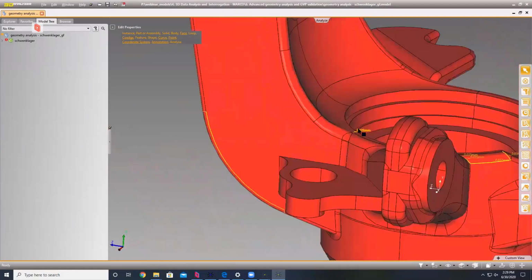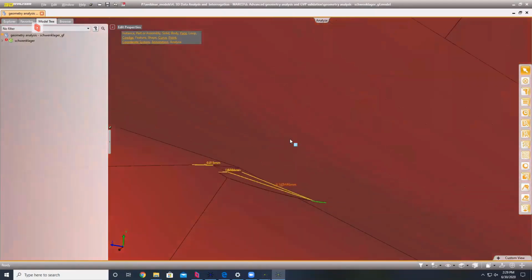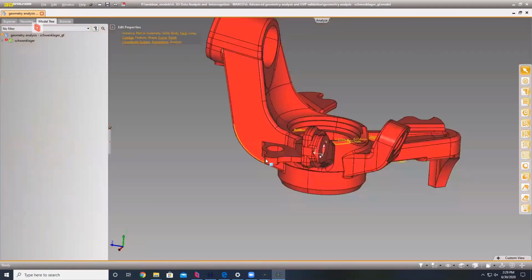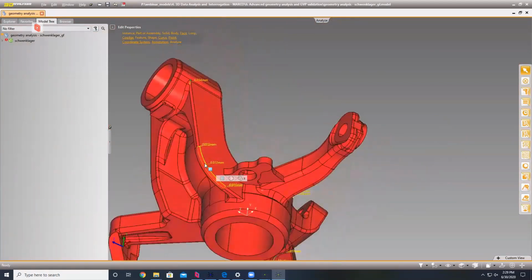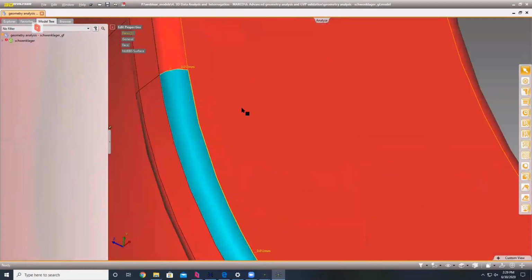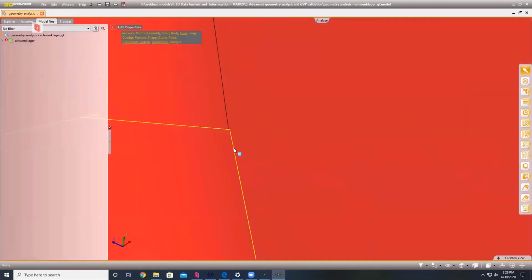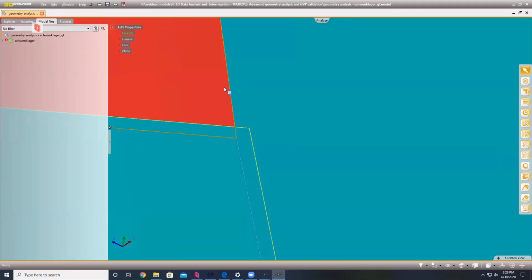So far, these yellow ones are just imprecisions. By that, I mean the precision of how this face is joined to this other face, for example. You can see the interface here, they're not exact. In fact, if you click both of these, you can see how there's a gap between them. So topologically speaking, they are connected.